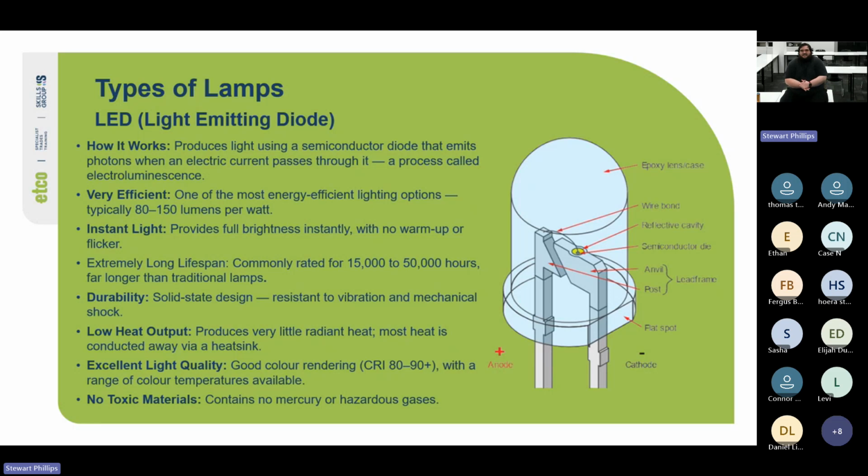When you're talking about when the sun comes down, that's what we call daylight harvesting. Daylight harvesting is where you have an IR sensor or a light sensor that senses how bright the incoming natural light is. And as the light dips, it turns the light on and increases the brightness of the light. It's used a lot in hospitals, where they either have natural light or the light comes on, and in workshops, especially automotive workshops that have skylights. If it becomes overcast and hard to see, they will turn on and ramp up the high bays so that the mechanics still have good light to work on the cars. So yeah.